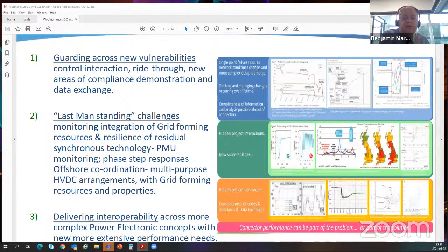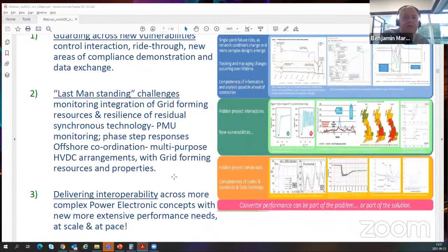So where you're delivering solutions such as inertial solutions, you need to be very cautious of ensuring that where you're having to introduce current limiting, which is almost inevitable in those solutions to guard against the rating of the converters, you need to be comfortable you're not introducing phase disturbances which are going to destabilize your existing synchronous contributions, and the devices such as PSSs are being aligned with them.